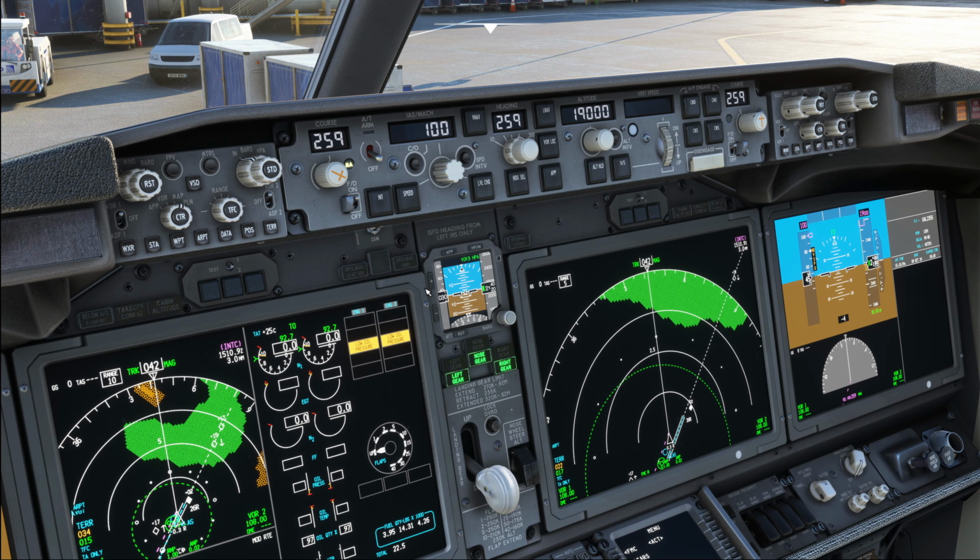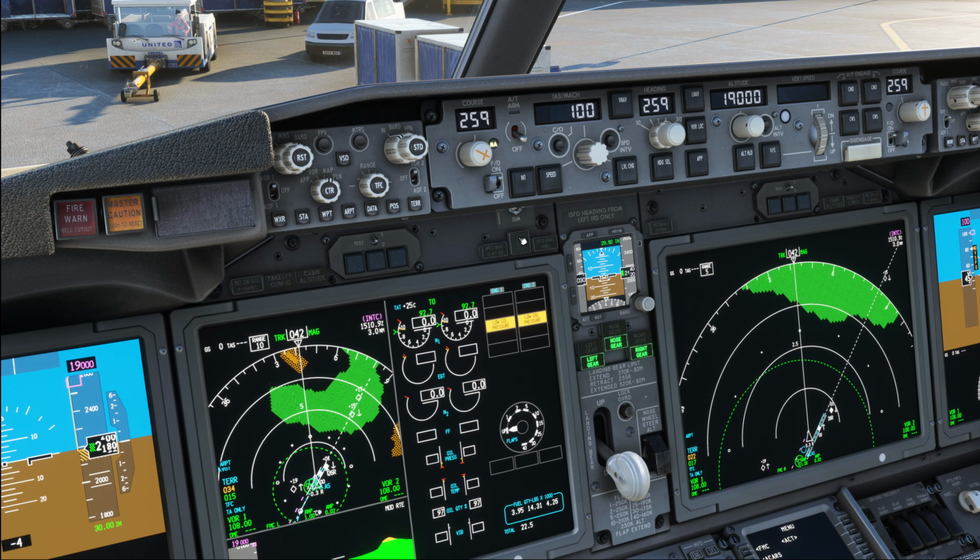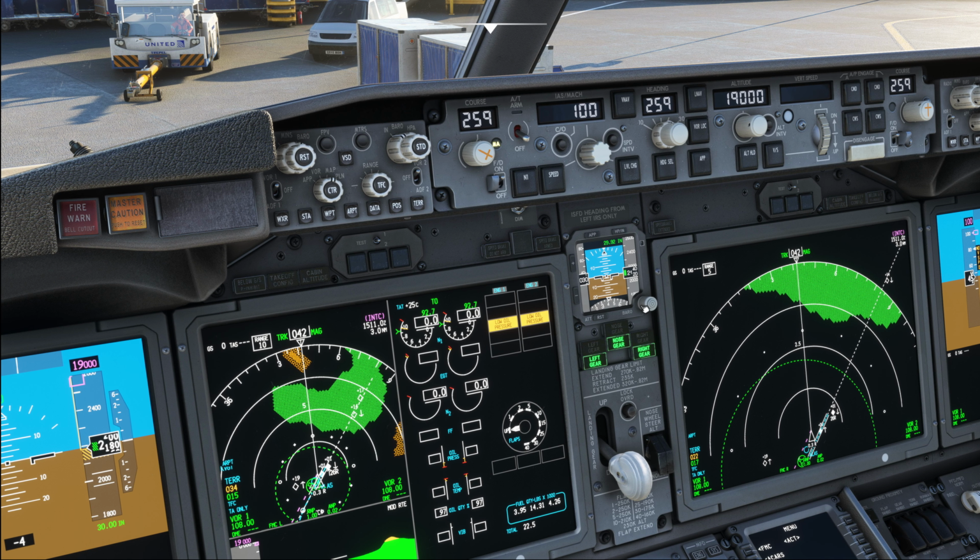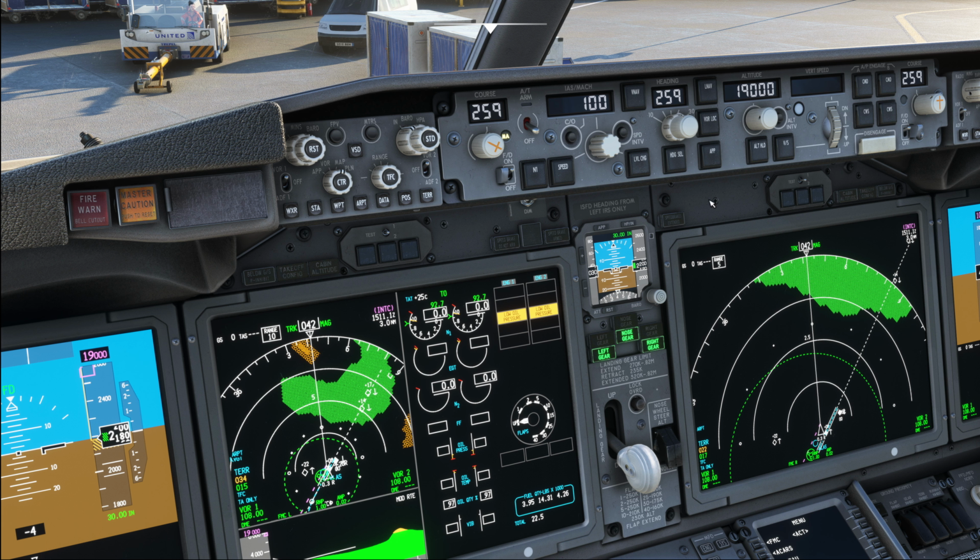So, moving on then, we have the ISFD, Integrated Standby Flight Display, over here, where we are going to make our altimeter setting to the same setting that we did on the primary altimeters, and once this is done, we are going to compare the 2 indications, 2180 here, 2000 over here, and those have to be within 200 feet of one another so that we're allowed to fly.